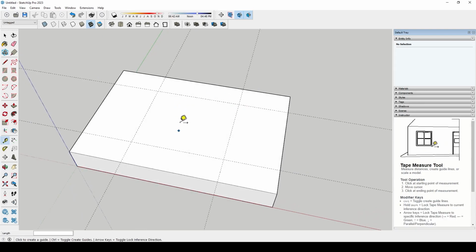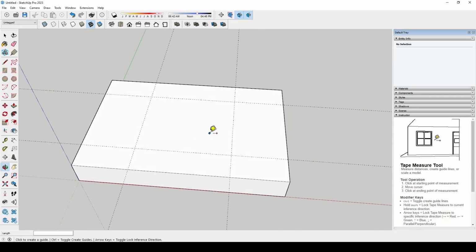And this is very useful in SketchUp, because if anything that you bring in from your import doesn't work, you can just make guides from known points in space, just like I did there, a meter from here, meter from there, 2 meters from here, 2 meters from there. And that gives you something that we can now draw lines over. So let's look at that together.